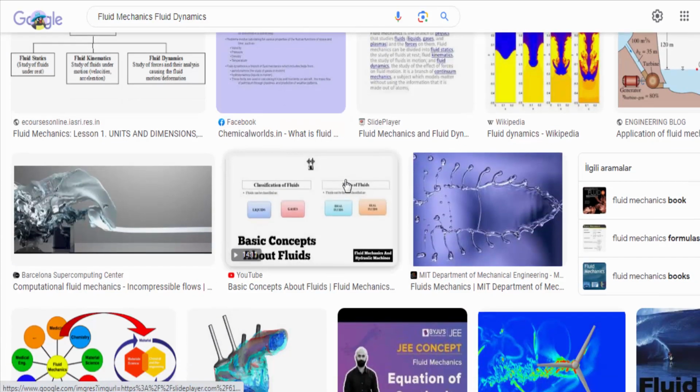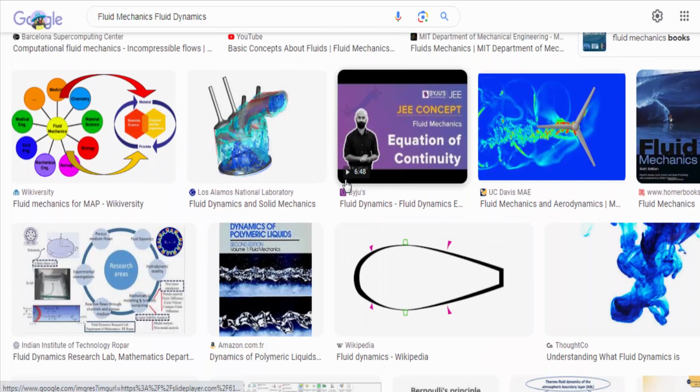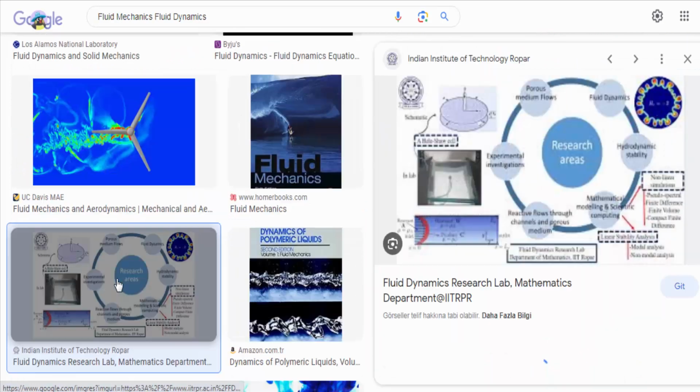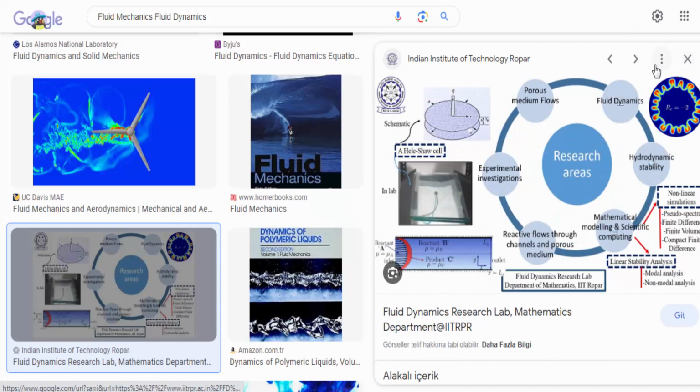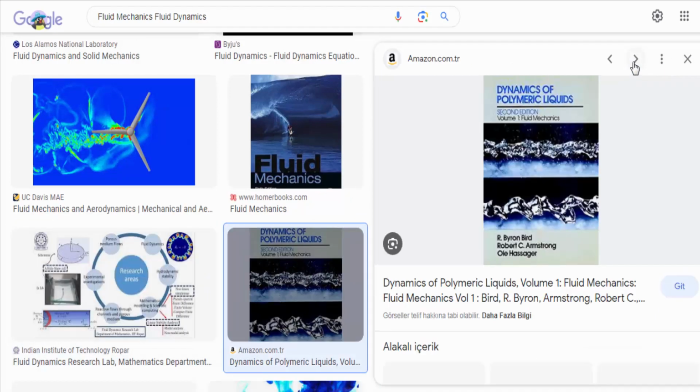Reynolds number. It is a dimensionless parameter used to characterize the type of flow, laminar or turbulent, based on the ratio of inertial forces to viscous forces in a fluid. The critical Reynolds number for the transition between laminar and turbulent flow depends on the geometry and flow conditions.